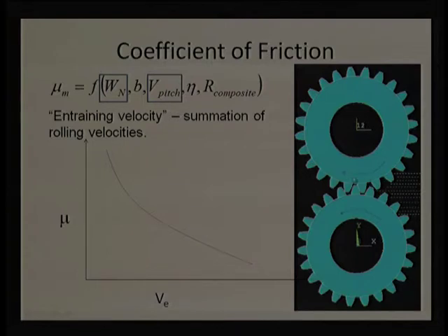With rotation, a dragging action on the liquid will happen, and more dragging action when there is higher and higher velocity. Obviously, this is more like a pumping action. This liquid lubricant is going to get pumped from this side to the other side, and that is going to generate more and more lubrication.